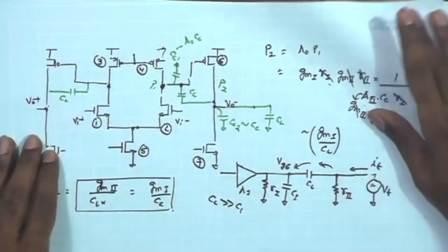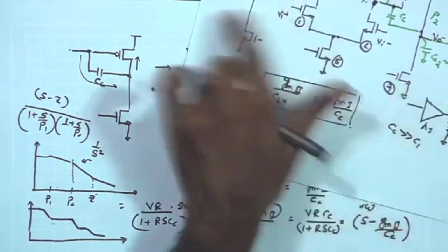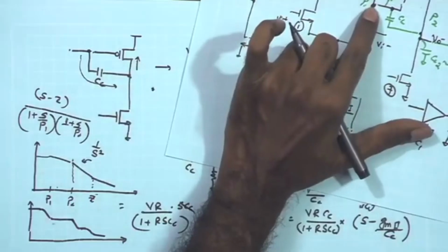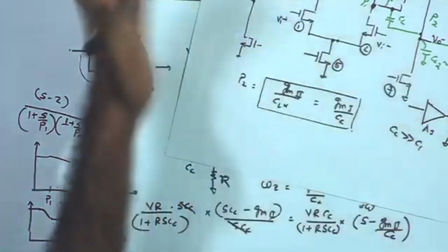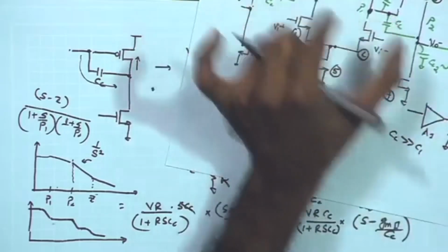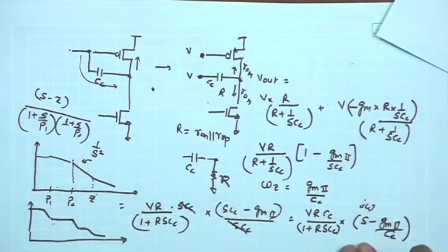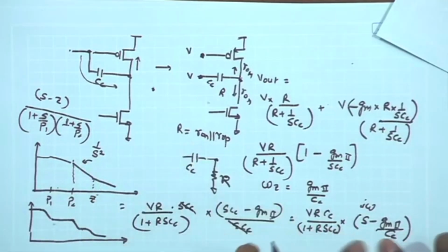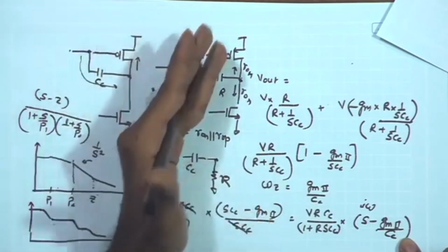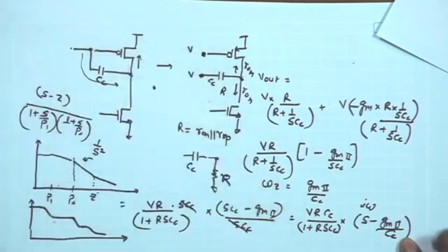And there again you can find out the exact expression of 0 coming in the numerator along with the terms in the denominator, factor them out and get the expression for the exact poles, and there you can take approximation and arrive at more exact value of these poles. So, here while considering the effect of 0, just to show the mechanism of originating of the zeros, we are using this model while ignoring its connection with the previous stage and the impedances provided by the previous stage.